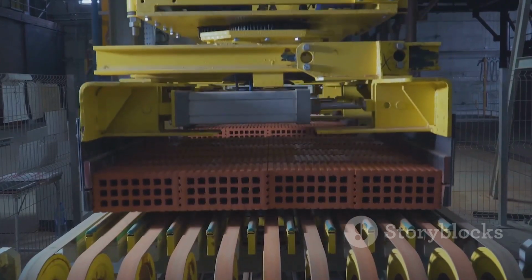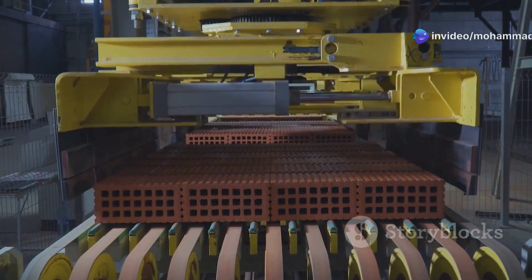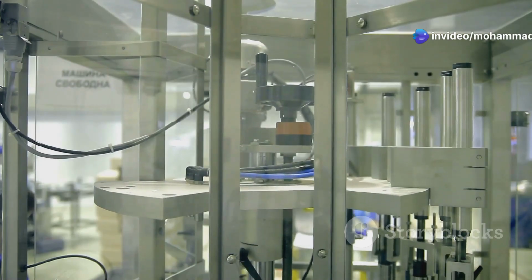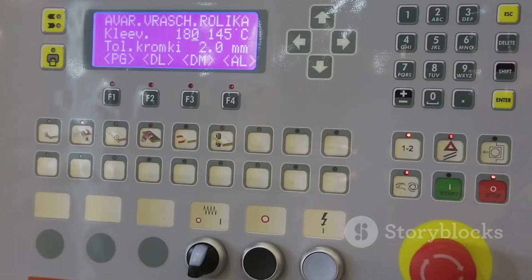Firstly, we need to define our inputs. Sensors detecting the presence of objects on the belt. Next, we configure outputs, actuators controlling the belt's movement. Finally, we establish the logic. If a sensor detects an object, start the belt. If no object is detected, stop the belt.